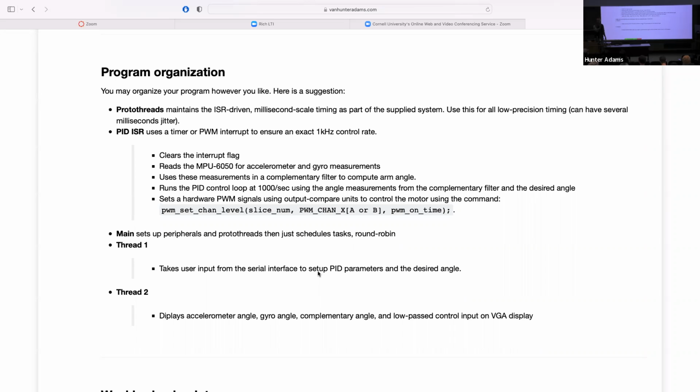And then as you move this around, you can say, are my gains set such that, oh, I don't know, my proportional gain is just always overwhelming the other two contributions to the controller output, which is valuable information to know, right? It would be interesting to watch as the thing balances, how do the weights shift among the three contributions to the PID controller? So you might consider adding that. You don't have to, but it would be interesting, and I think it would be helpful for debugging.